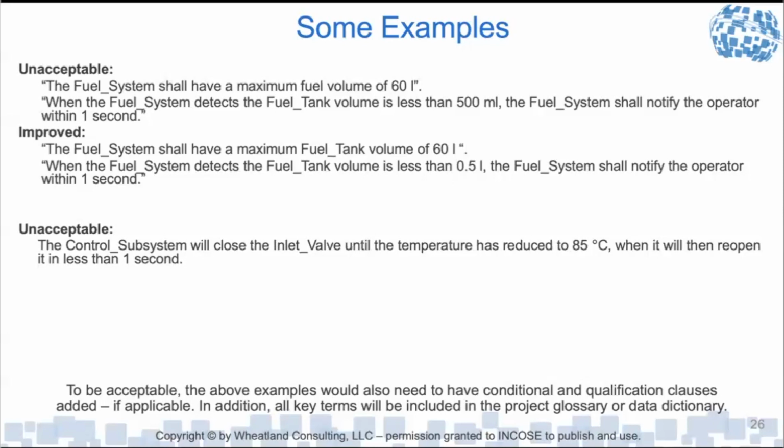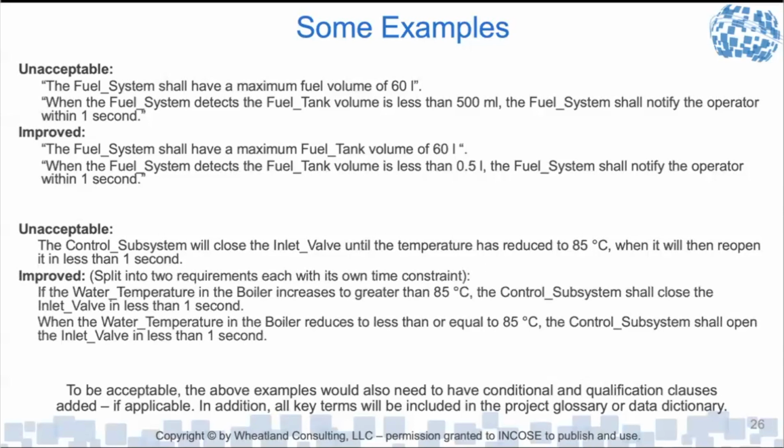statement. So when we rewrite this as two requirements: if the water temperature in the boiler increases to greater than 85 degrees, the conditional statement, then the control system shall close the inlet valve in less than 1 second. And then a separate requirement: when the water temperature in the boiler reduces to less than or equal to 85 degrees, the conditional statement, the control system shall open the inlet valve in less than 1 second. So both of these are going to be our separate actions. Each will be verified independently.